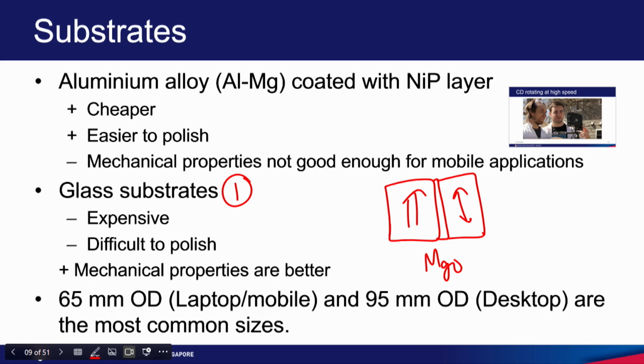There may be some gain if you increase the thickness of the reference layer, okay. But beyond a certain point, there are 2 problems. Let us say you make it only 1 nanometer, then you may not achieve sufficient spin polarization, that is a problem.